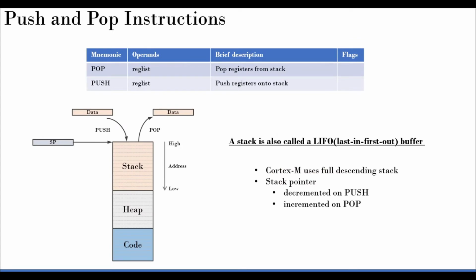This is the most fun part. Very interesting aspect, and you will love this because there are a lot of useful applications for it. Push and pop, as the name suggests, is something like you're pushing something and then popping something out. The literal explanation is here. When you say you are pushing, that means you are pushing the content of registers to stack memory, and popping means you're popping the content of the stack back to the registers.